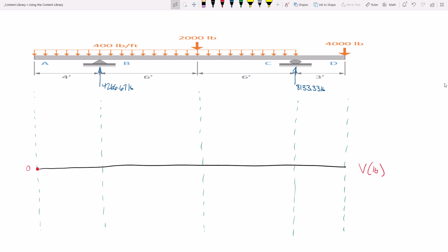All right, distributed load. Okay, how much total load is between A and B? It's 400 pounds per foot for a distance of what? 1,600. What direction are those arrows pointing? Down. Whenever you're drawing a shear diagram, you do what the beam tells you to do. I'm looking at the beam and it's saying, Greg, go down. So I'm going to go down, right? My first name's Greg. We know each other. That's a joke, not a very funny one.